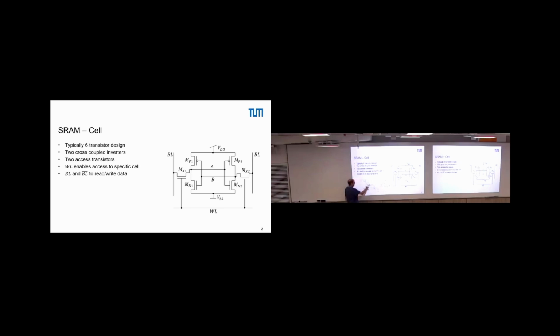So any tiny noise fluctuation that we always have on our circuit would move us out of this point. This is called the metastable point, because as long as nothing changes and we are perfectly in this point, we are stable. But any small shift out of the state moves us into one of the stable states. That's called the metastable state.